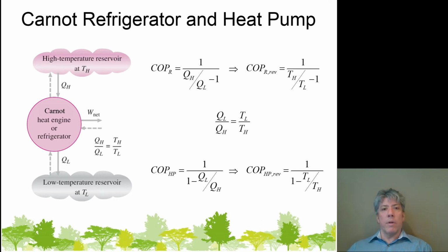Okay, and so what they would do is put air out of the vents that was at 90 degrees, 85 degrees, something like that. Warm enough to heat the house for sure, but if you stand over it, it just feels like cold air blowing on you because we human beings have water on our skin, and as we stand over a register like that, we feel the air coming out, it feels cold because it's pulling energy away. The water is evaporating off of our skin, and so we sense heat leaving our body rather than coming to our body, and we're like, oh, this is cold air coming out of this register.